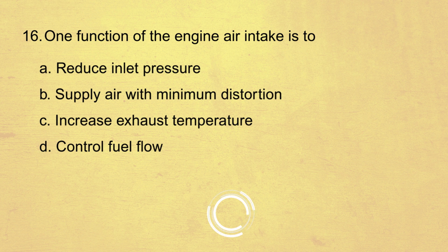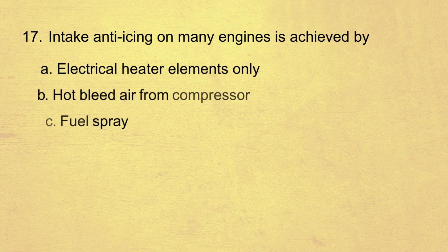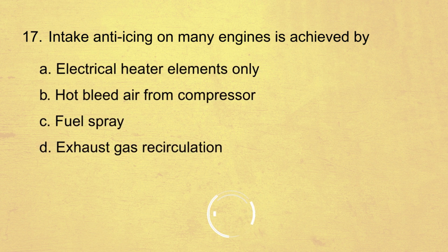One function of the engine air intake is to supply air with minimum distortion. Intake anti-icing on many engines is achieved by hot bleed air from the compressor.